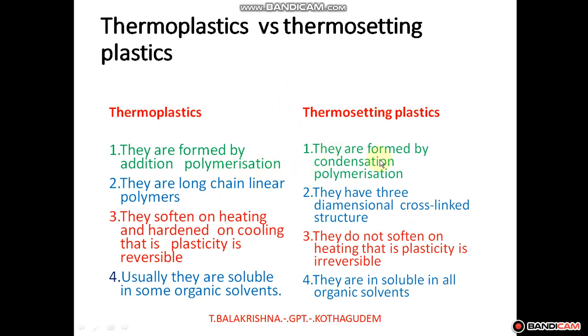Here, the difference between these two is that thermoplastics are prepared by addition polymerization, and thermosetting plastics are prepared by the condensation polymerization reaction. We already learned in the previous part the difference between addition and condensation reactions. In every addition reaction, monomers are added in a linear manner. In every condensation reaction, they are added in a cross-linked manner.